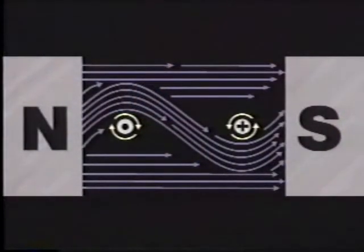Because current flows toward you on the left side, the flux lines rotate in a clockwise direction. But since current flows away from you on the right side, the flux lines rotate in a counterclockwise direction. The alternating direction of current flow in the U-shaped armature allows the motor to put magnetic flux line interaction to work. Here's how. On the left, the armature flux lines distort the field flux lines, and magnetic push moves the